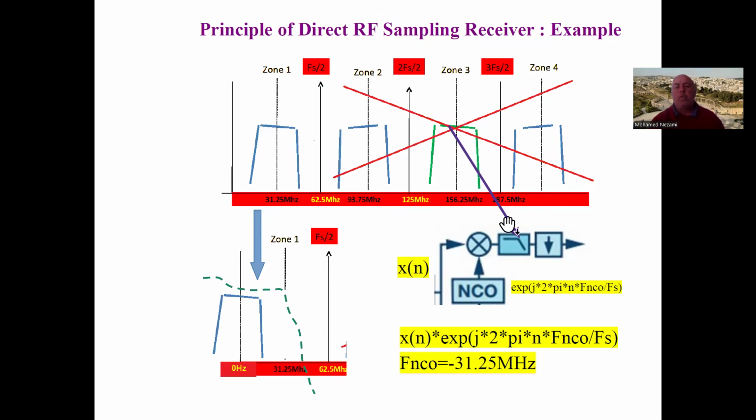And then, of course, it's oversampled, meaning the sample rate in here is way above the minimum required samples for the symbols to be decoded. Therefore, you can start throwing out samples to reduce the complexity of the DSPs that follow. That's decimation filtering. We introduced that in the last lecture and showed how the signal-to-noise ratio is improved by 10 log of the decimation ratio.